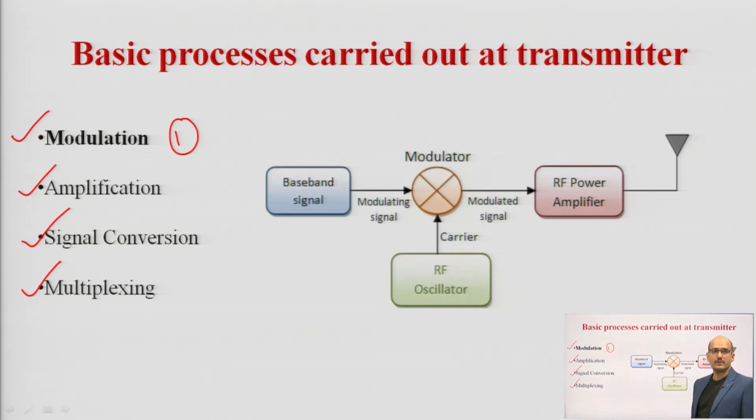Now, what is modulation? You already studied this in communication systems, but I am going to recall it because it is required here. Modulation means you modulate the carrier signal as per the message signal, because the data coming from the transducer or signal conditioner is your main data signal or information, and that information signal has low frequency.